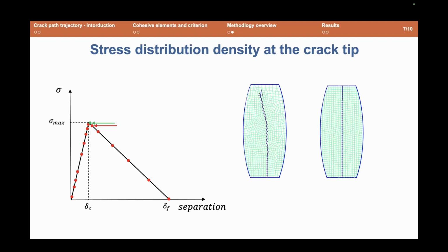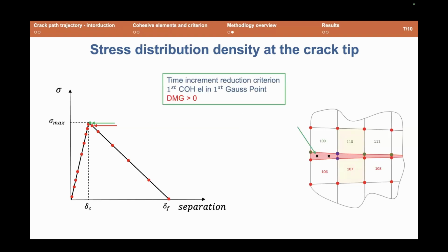Often it happens that they move on somewhere, and then principal stresses are actually introducing some error with their versor. So we get a zigzag pattern, and the crack generally has a good direction, but with this zigzag. To avoid that, the green point would be ideal for all the increments. We did that by using a subroutine.